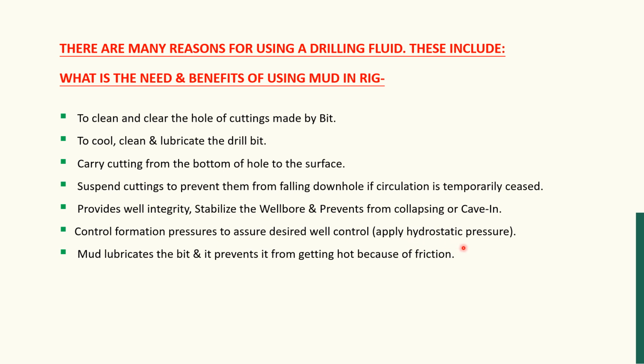I think, according to me, this is the most advantageous feature of the drilling mud: to create the hydrostatic pressure to control the formation pressure, so that a blowout does not arise in the well. The next one is that the mud lubricates the bit and prevents it from getting hot because of friction. So this is also an important feature.